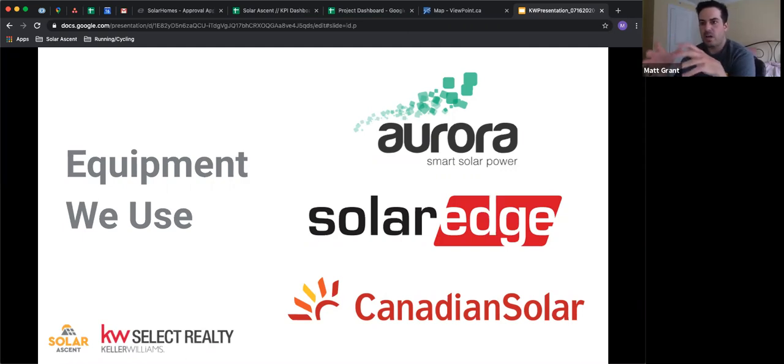The old style solar PV system was string based. Think of Christmas lights when you're a kid. When one bulb goes out, the whole string of lights goes out. So that's where a bit of baggage around solar comes from: if one panel went bad or a bit of shading covered one panel, it would drop the efficiency of the whole system and limit your production.